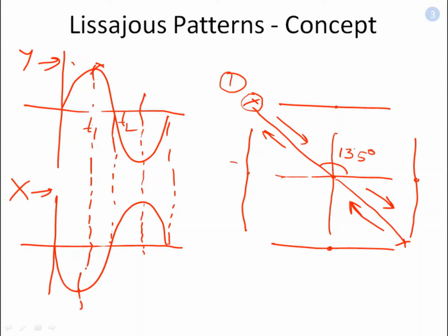So this is the scenario when both the signals have the same amplitude and frequency, but they are 180 degree out of phase. So the pattern you will watch on the CRO will be a straight line at 135 degree with the x-axis. Let us go a little ahead, where I will discuss if both the signals are of the same amplitude but the frequency changes, how it will impact. Let us draw it carefully.